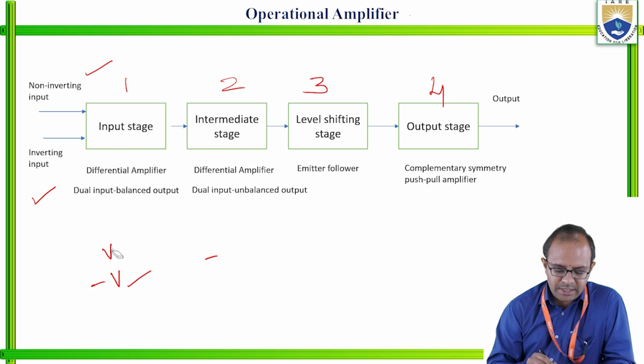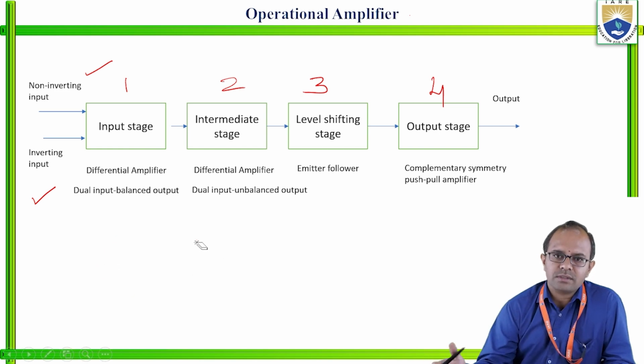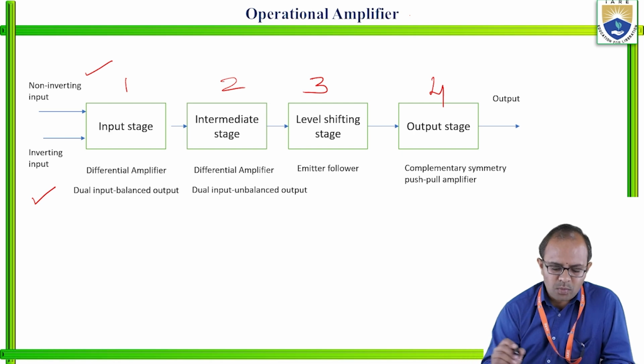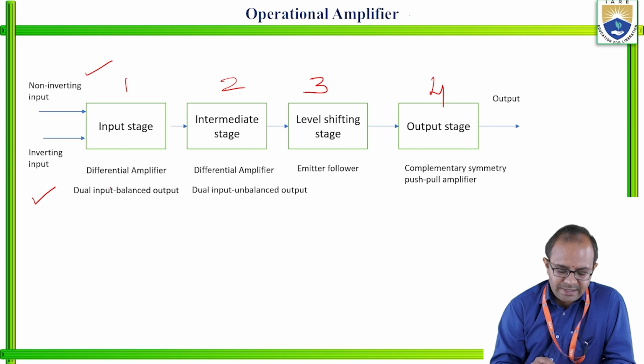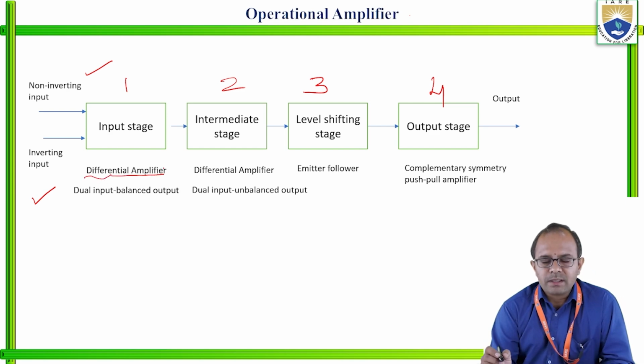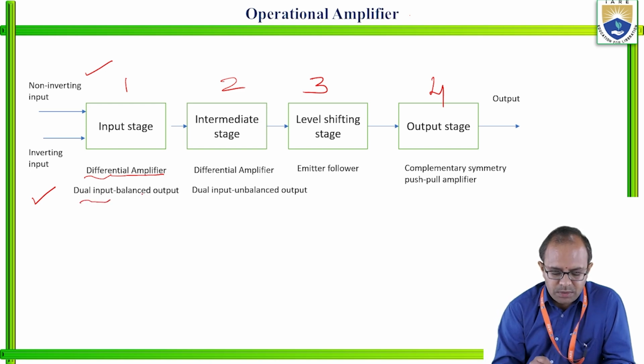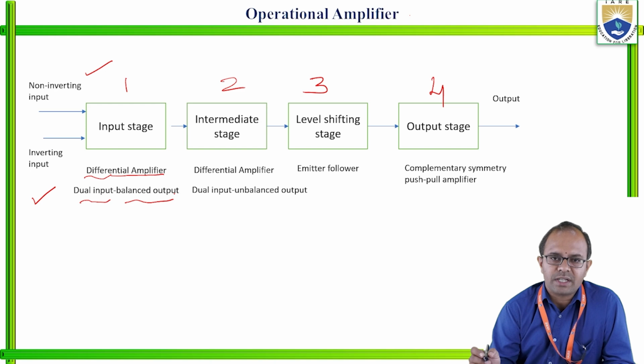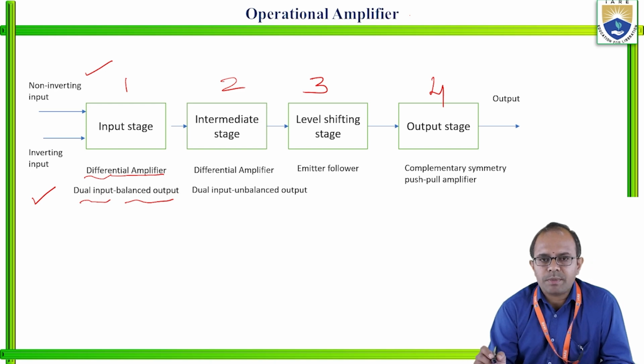These 2 are the inputs that we are going to provide to the input stage of the operational amplifier. And what is the input stage? The first stage. It is supposed to be a differential amplifier. So do remember, the input stage of the operational amplifier is going to be the differential amplifier, preferably the dual input, balanced output configuration.